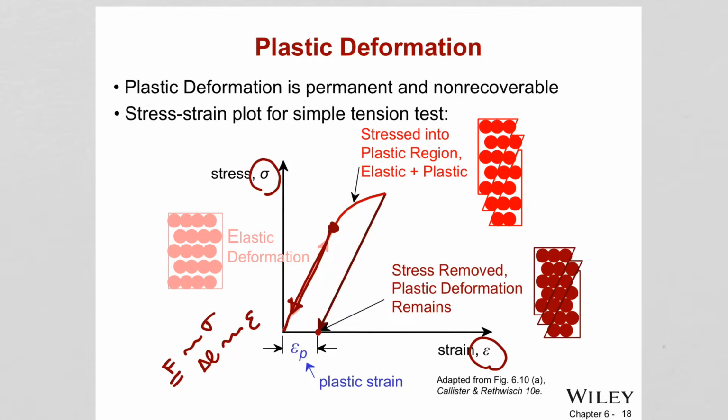And later we're gonna see there are certain atomic regions, certain atomic planes that require the lowest amount of energy to move. Those are the ones that slide initially over each other, and dislocations are helping it. So by the motion of dislocations, the material is deforming plastically.